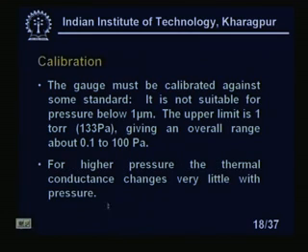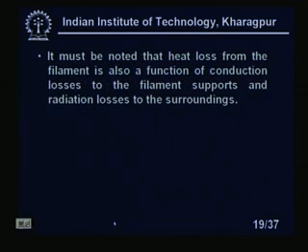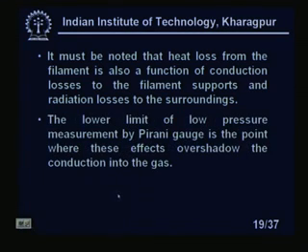For higher pressures, the thermal conductance changes very little with the pressure. It must be noted that the heat loss from the filament is also a function of the conduction losses to the filament supports and radiation losses to the surroundings, right. The lower limit of the low pressure measurement by Pirani gauge is the point where these effects overshadow the conduction into the gas, right.